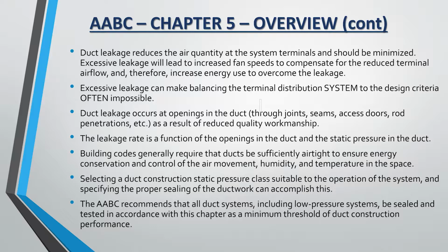Excessive leakage can make balancing a terminal's distribution system to the design criteria often impossible. We've had more than enough exhaust systems. Get the whole thing done, systems in, we start balancing it. And where they terminated all the little exhaust grilles, they flanged them between the ceiling, and it's compromised right there. Next thing you know, we've got 5%, 10% leakage at every one of them, or the telescopic fittings. The ductwork's all sealed, but when we get to the end, it's important that all the way to the terminal, like it says here, it be sealed and help reduce